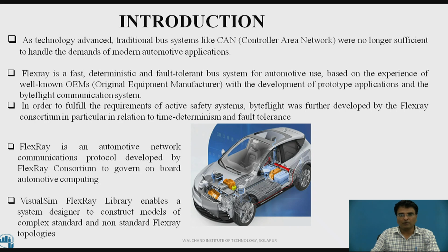With the development of prototype applications and the ByteFlight communication system, in order to fulfill the requirements of active safety systems, ByteFlight was further developed by the FlexRay consortium, particularly in relation to time determinism and fault tolerance. FlexRay is an automotive network communications protocol developed by the FlexRay consortium to govern onboard automotive computing. The VisualSim FlexRay library enables a system designer to construct models of complex standard and non-standard FlexRay topologies.